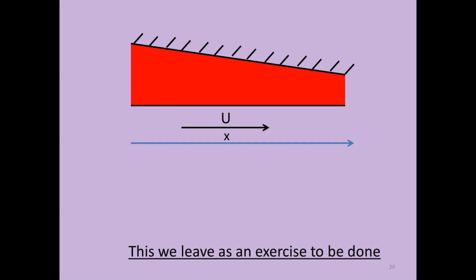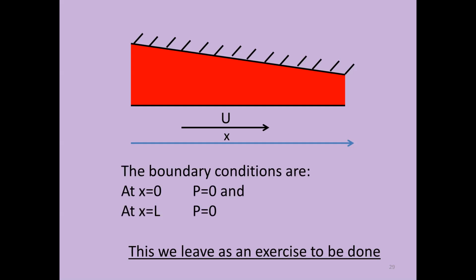This pressure can be integrated over the surface area to give an equivalent value of load, and this load is going to support the external load acting on the system itself. So this is how the fluid film lubricated bearing is going to work. And the governing equation obviously was displayed earlier.